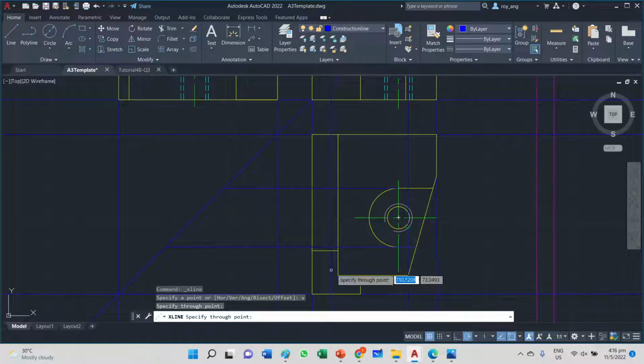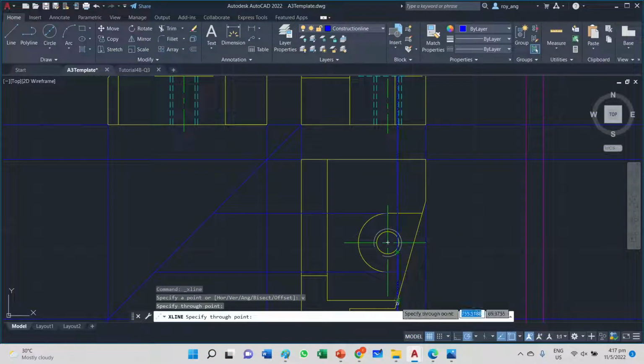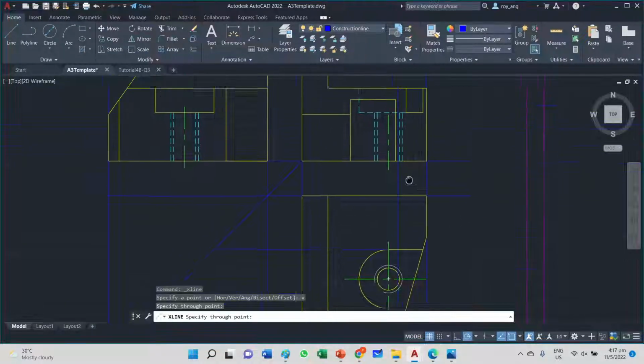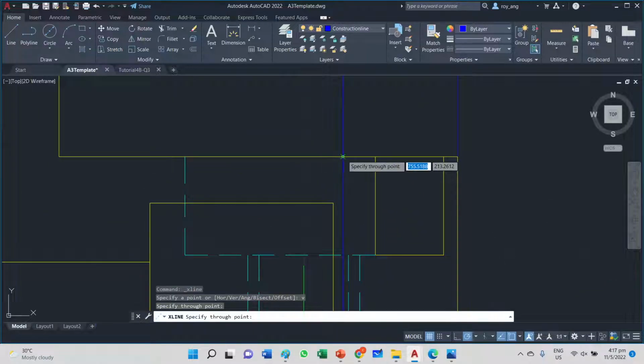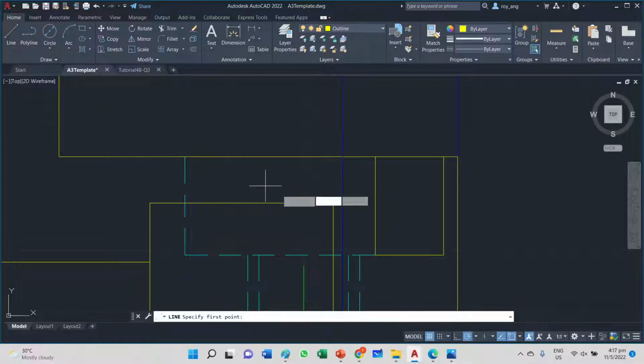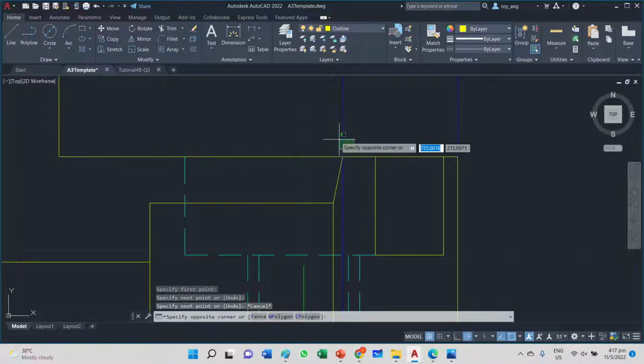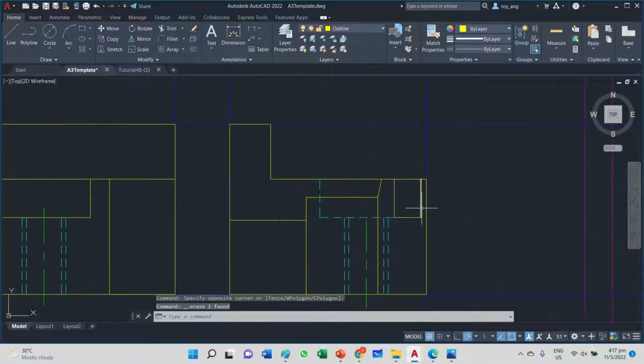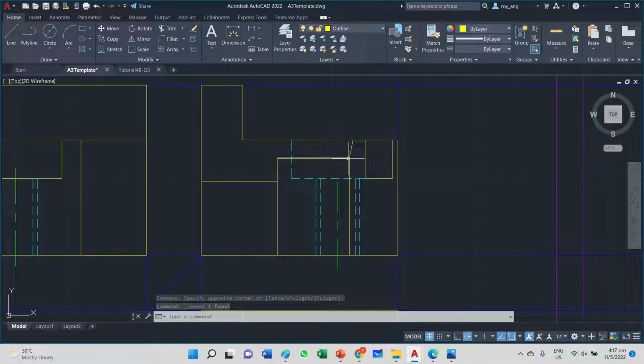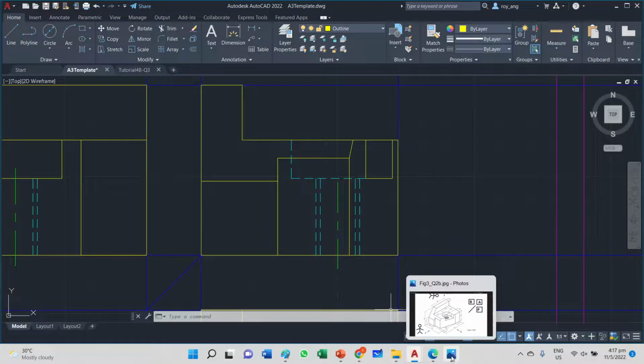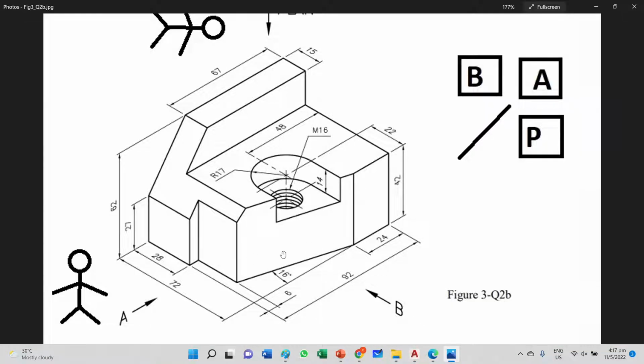But now that my plan view is completed thanks to my end view, I can then know where is the intersection point, and I can project it up. And I know it intersects this point. So therefore, I can now complete my front view with this outline. And this outline is sloping at an angle. Okay, so you can see this from here. There is a slope, and then there is the cutout, there's a U shape, and it goes about. So this region is this region looking from this angle, and that's what you'll see.